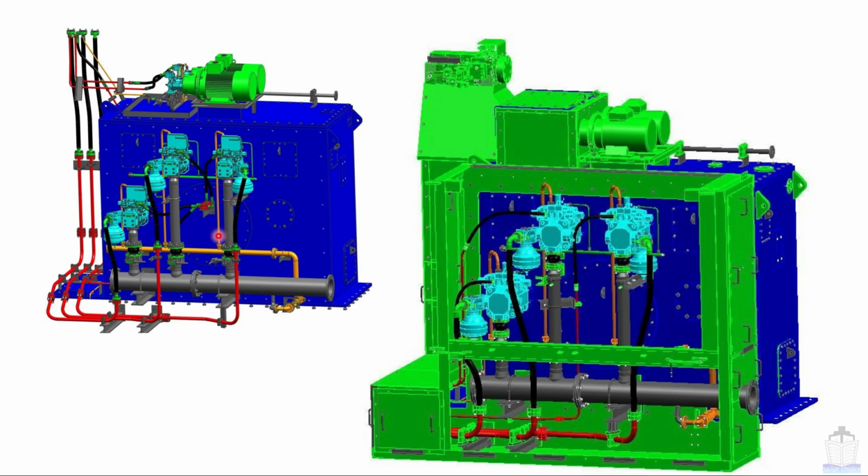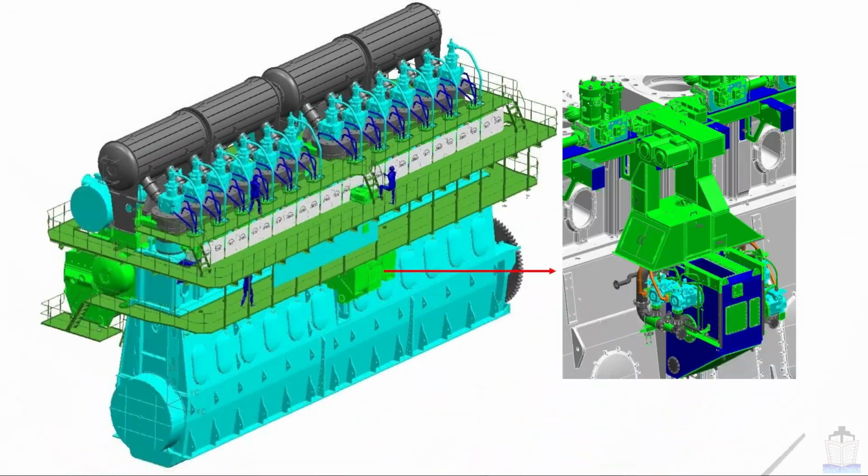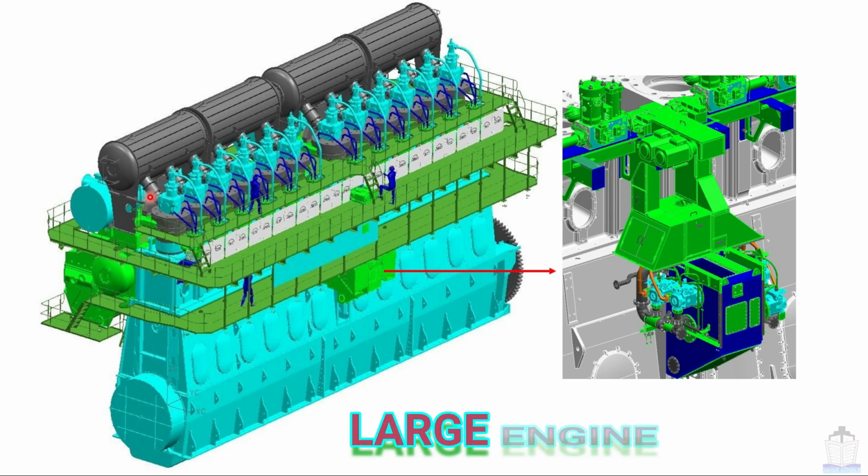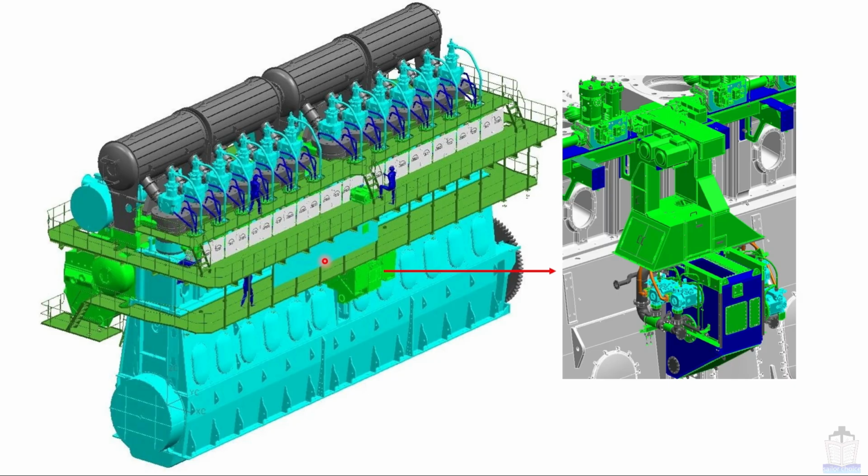This is shown in fully open condition and this is shown in the covered condition, except for these three pumps. This is the inlet manifold for the hydraulic oil, and all these are outlets going to the safety block. Now if you talk about the larger engine, then obviously it will have more cylinders. In those types of engines, the hydraulic system pump assembly is situated in the middle of the engine, as you can see clearly in this picture.